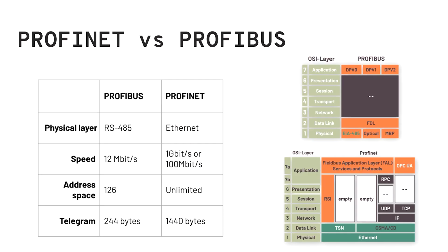So to put the comparison in a table, you see that what's different between Profibus and Profinet is mainly the two layers, right? You have a data link physical that's proprietary here, and here's Ethernet based. And since you have Ethernet based here, you have to also ensure that your transport protocol, here the transport is very specific, so you don't have to worry about the routability or the way you transport data, the application layer takes over everything. Here, since it's Ethernet, you need routing offered by IP, and you need the way to transport offered by TCP, or you can also use UDP.